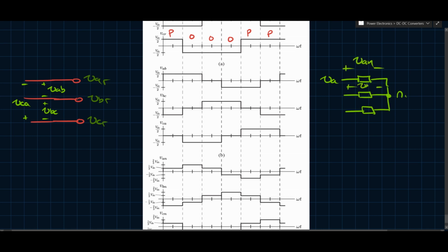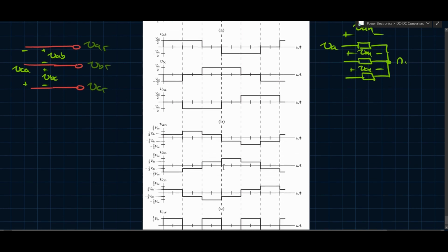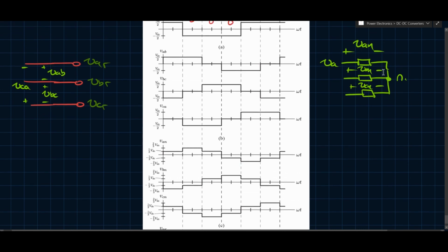This voltage here is VBN, and this one here is VCN, of course. And so, again, it's useful to have all these equations and waveforms and relationships to understand what's really going on. But you see that this is approaching somewhat of a sinusoidal behavior. So you want that, obviously. You want a 3-phase line to neutral, in this case, N being this neutral voltage that would be somewhat resembling a sinusoid, such that you can reduce the amount of harmonics.